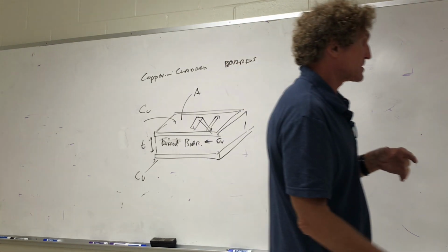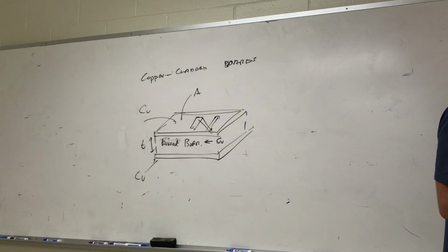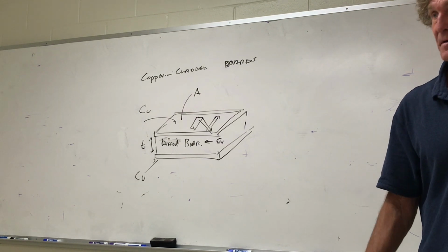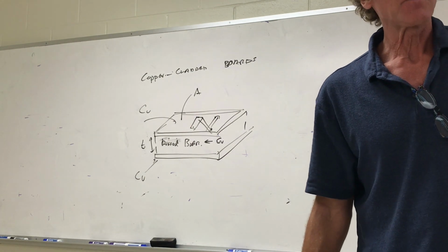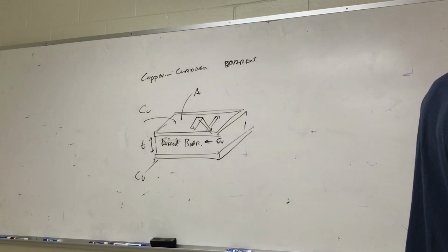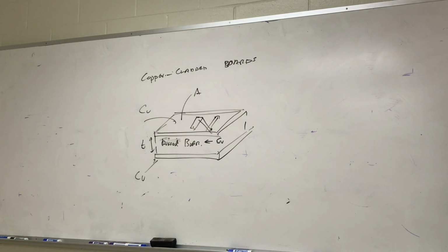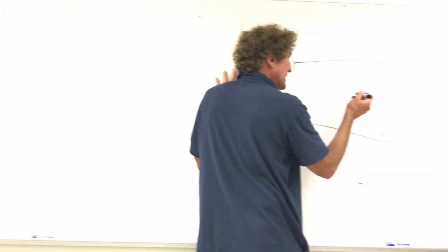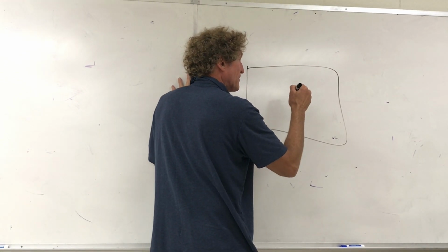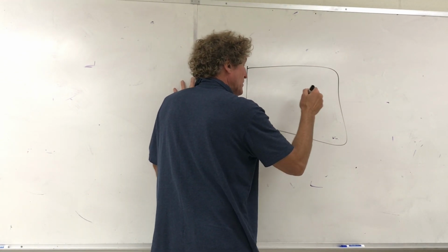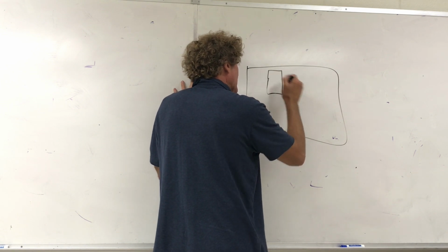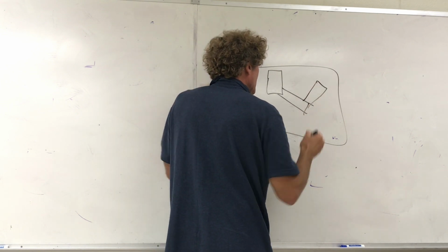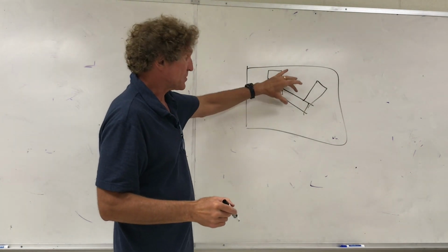So a photoresist is something they put on there, and they leave the photoresist everywhere they want the copper, and everywhere they don't want the copper, they develop it. They put either light on it, something like that. They can use an electron beam, it doesn't matter. So if you're looking top down at the copper layer, after they put the photoresist down and develop everything but what they want, you're going to be left with copper like here, here, here, and these are just electrical connectors with a certain width and a certain thickness.